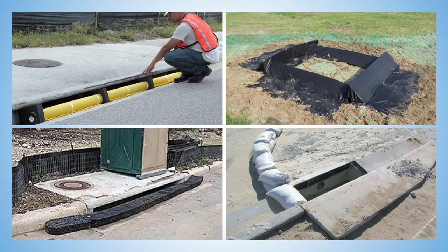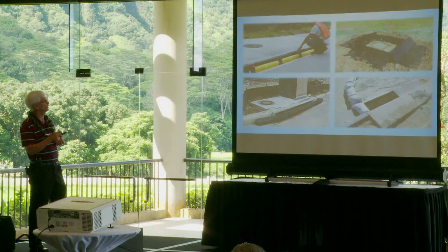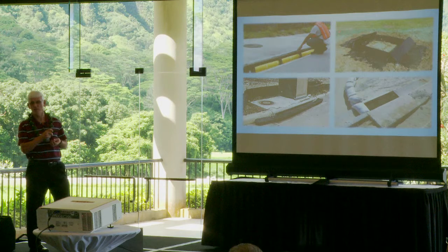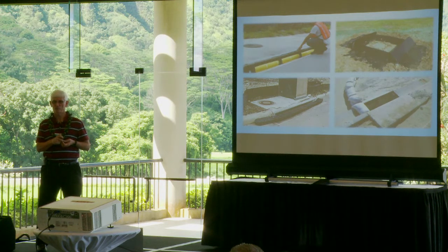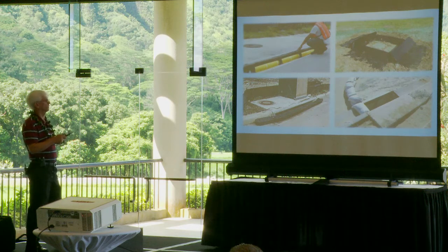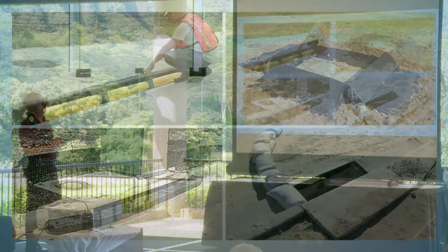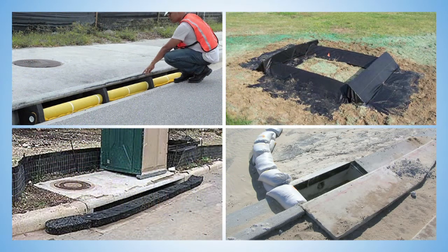This one I like. This one is essentially a piece of PVC pipe with almost like a foam pool noodle on it, wrapped in geotextile, and it has these wedges that go up in it, but it has this clear spot right here, so this allows overflow capability, and it's capable of trapping a lot of debris and dropping it out and still not causing clogging or flooding. This device basically allows water to pool up and drop over, almost like a rock bag.